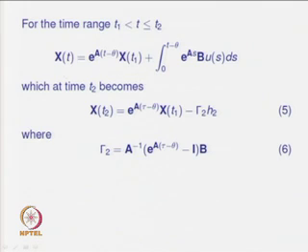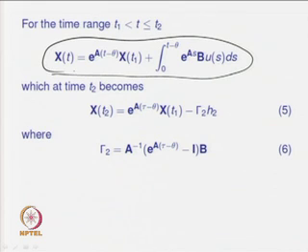That gives us the solution of the state equation for that time range in the form of x(t) is equal to e to the power A(t minus theta) x(t1) plus the integral with limits 0 to t minus theta of e to the power As B u(s) ds. So, u(s) becomes minus h2. Now, why am I writing t1 here? This t1 is nothing but theta. Keep in mind that t1 is equal to theta.